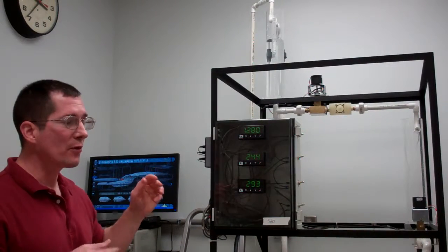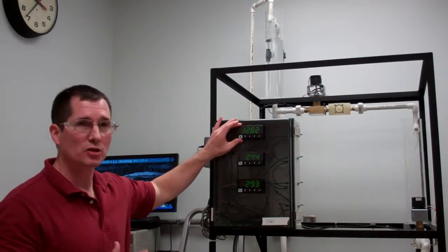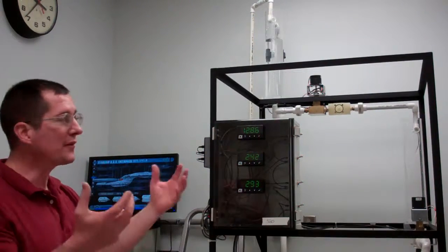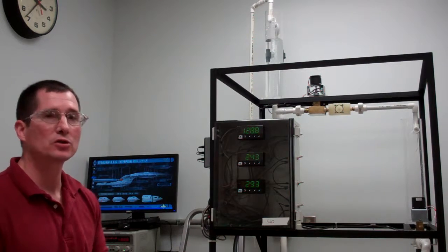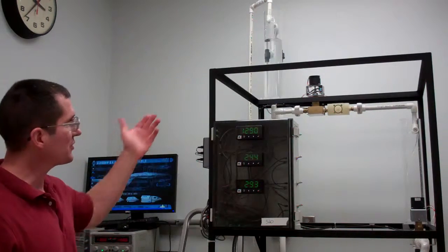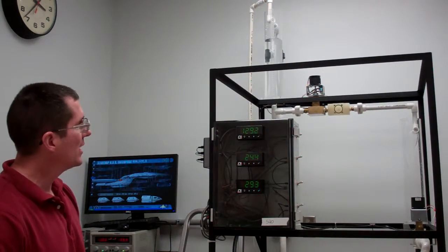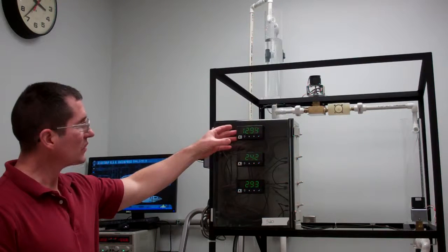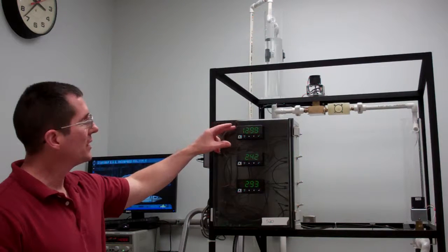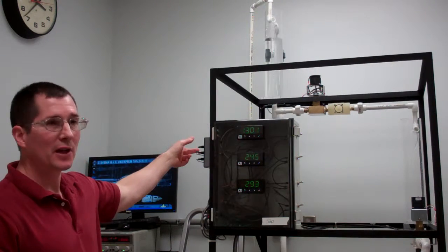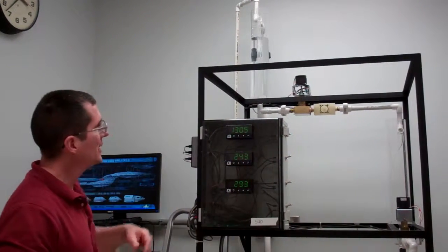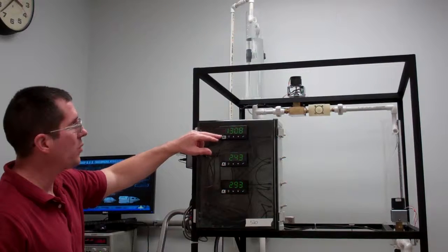In order for you to be able to program this controller so that it knows what to do when the level's too high or too low, you have to characterize your final control element, which is what we're going to do on this experiment. Of course, this final control element is going to be this control valve. And so you're going to look at how much power you have to send to the valve in order to overcome the inlet flow. Right now, inlet flow is at 1.4 liters per minute, and my valve is not giving me quite 1.4.